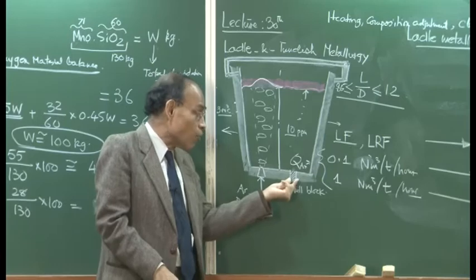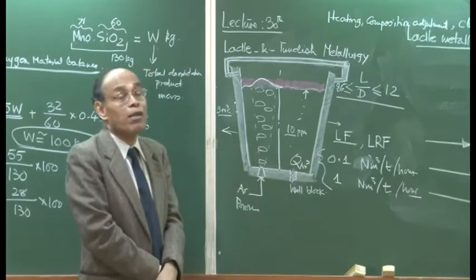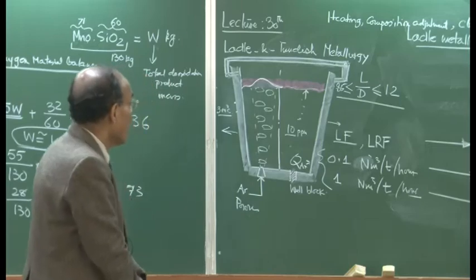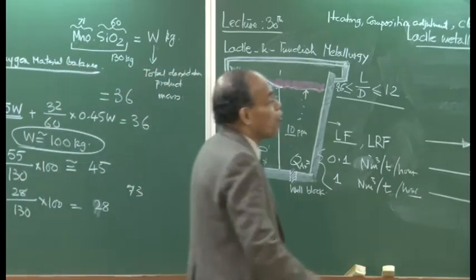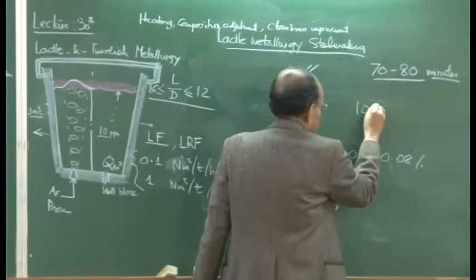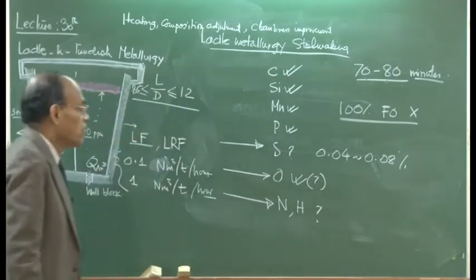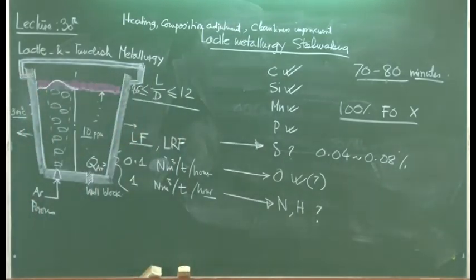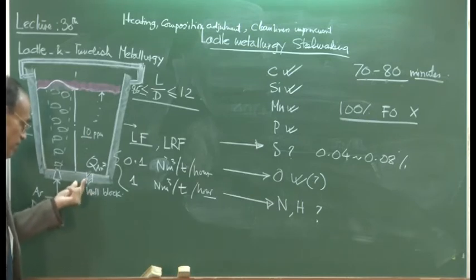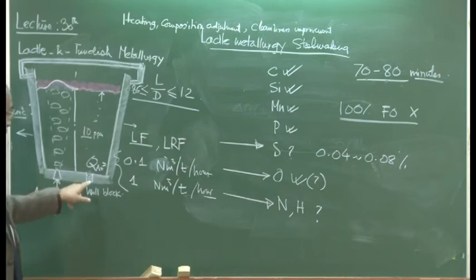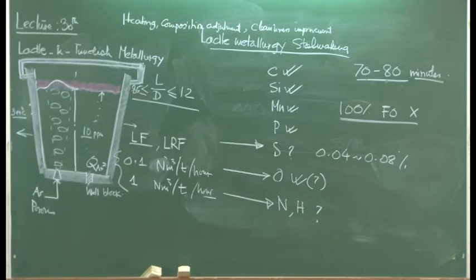So, the quality of the powder with which the well blocks are sealed is very, very important, because 100% free opening is rarely achieved in practice. Free opening, one or two hits in 100, you will find that something has gone wrong with too much temperature, or erroneous composition, etc., have resulted in the sintering of the powder, which is not giving free opening at all. So, it is very important for us. Okay, we will talk about this later on.